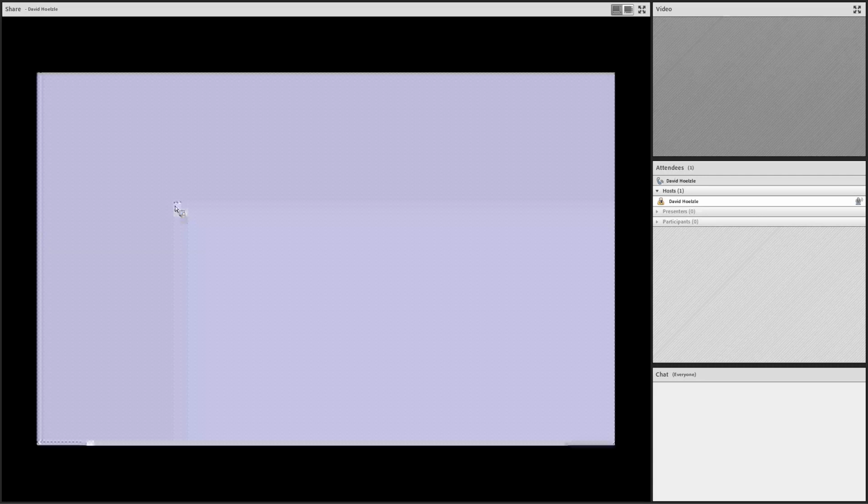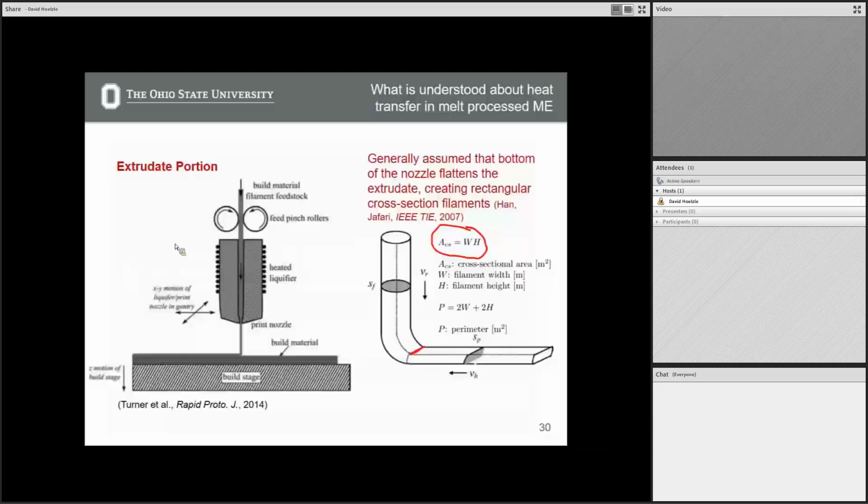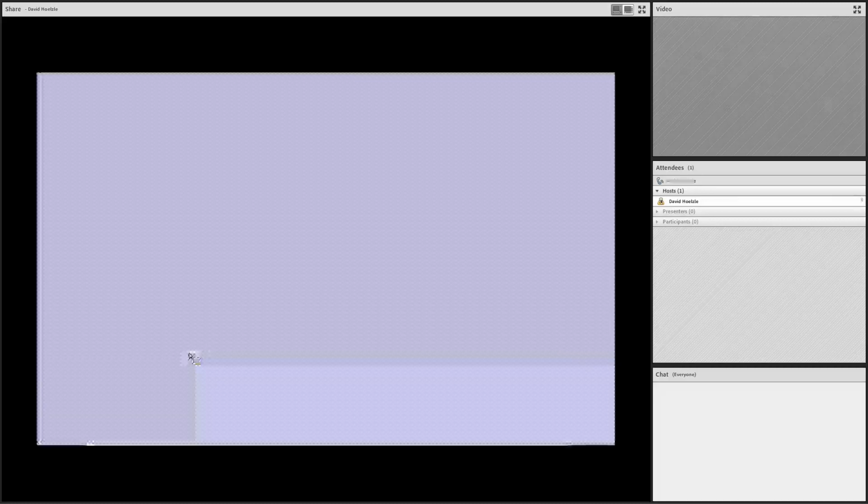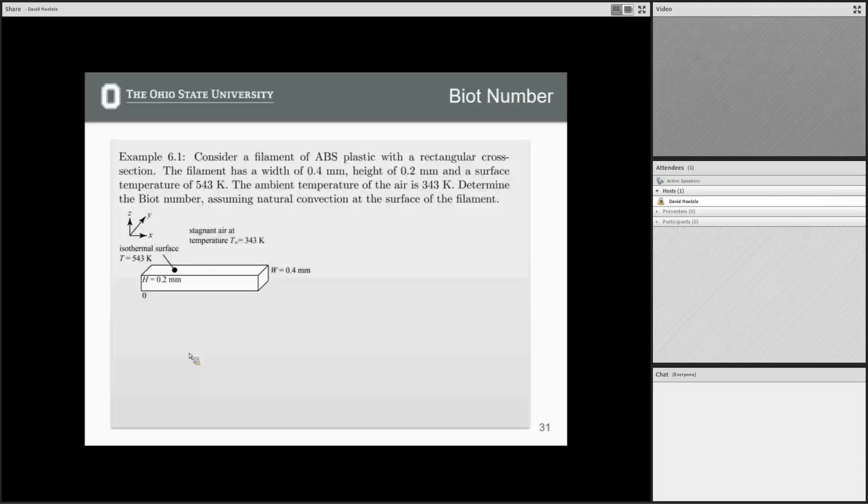Now the difference between this sheet architecture as compared to powder bed fusion is I know there are some material extrusion systems that will have fans inside the region to circulate the air, but the vast majority of them do not. Right? So if we just go baseline, we would say that there is no forced convection within this chamber, and any convection coming from the surface is from natural convection. I'll get to what this natural convection is in a second.